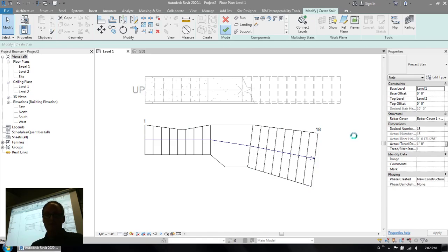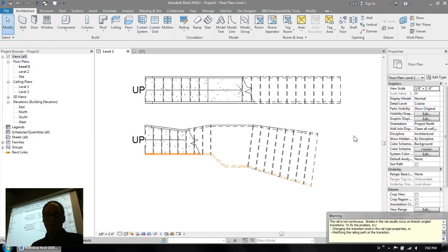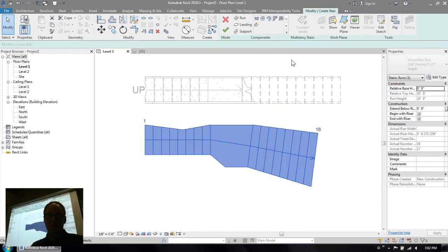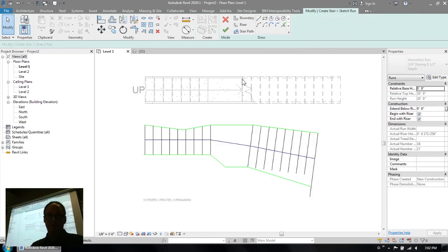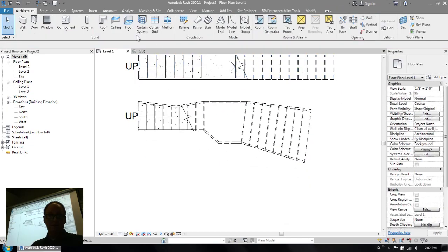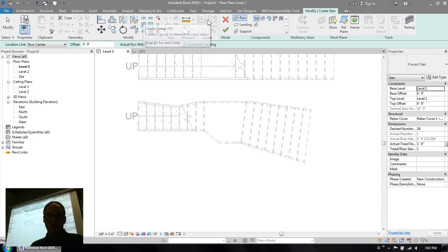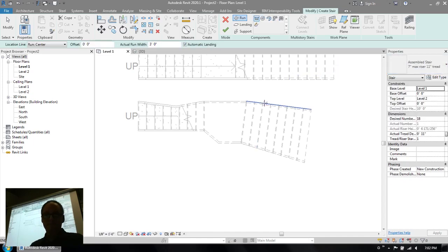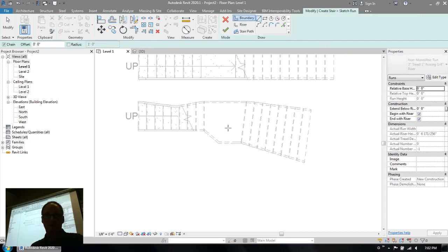Revit will generate the stair here in a few moments. Now, some rules about the boundaries. So here I'm just digging in and editing each layer. Let me just draw a new stair here with the sketch mode again. So going to stair, and I'm going to use the assembled stair here. So I'm building a wood frame stair. Before I start drawing my sketch for this stair, I'm already choosing to go with the assembled stair. So what I want to demonstrate here is doing it wrong.